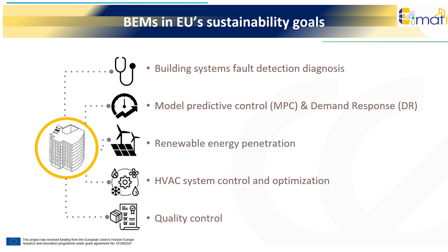Furthermore, this intimate relation between the BEM and the BMS allows the study of non-intrusive, low-cost optimizations of the latter. A calibrated BEM can be used to generate operational schedules and establish optimal set points for the building's HVAC system. Finally, calibrated BEMs provide a sound foundation for the design and evaluation of building retrofits. Their application as baseline models can be used for quality control in construction and renovation.